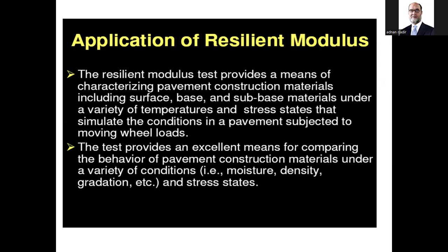It depends upon the size of the sample. Now, as compared to this, resilient modulus is a mechanistic behavior of the material. Material stress-strain is defined in this type of test. In CBR, we had stress and strain, but it was not strain like it was just unidimensional, and it was dependent on too many constants and too many assumptions. Just facing a dead load, facing a surcharge load, testing after 4 days of soaking. So these are the tests.